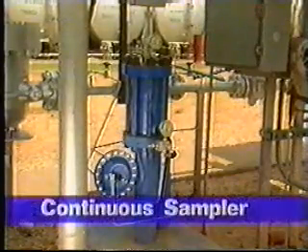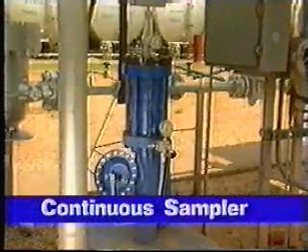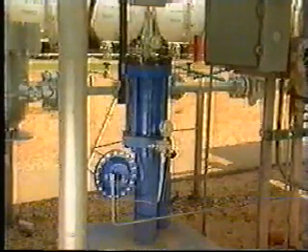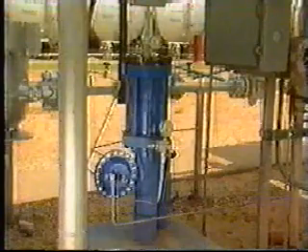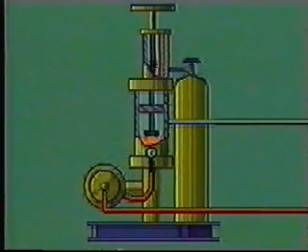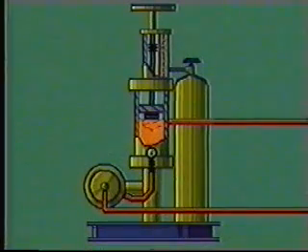Samples should be taken continuously from an NGL stream. The sampler is then a part of the secondary element. A continuous sampler takes samples at intervals from the meter tube. One word of caution, however: since NGLs tend to layer over time, a mixing device should be used to mix the NGLs before taking a lab sample.